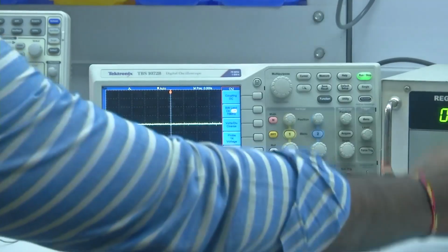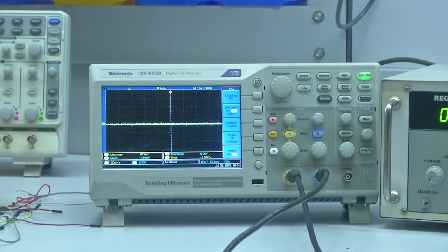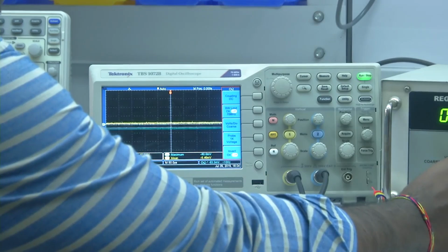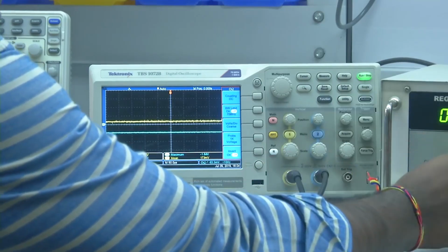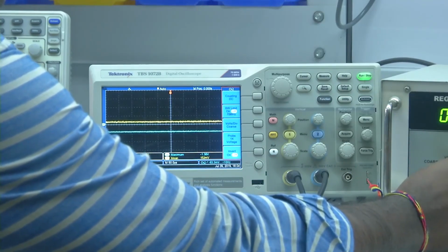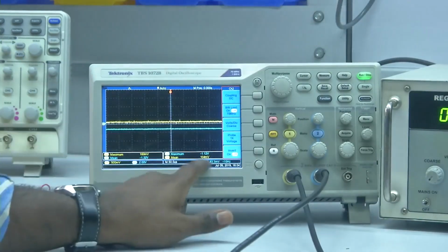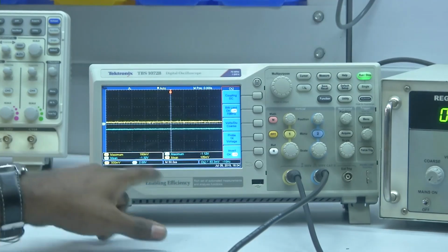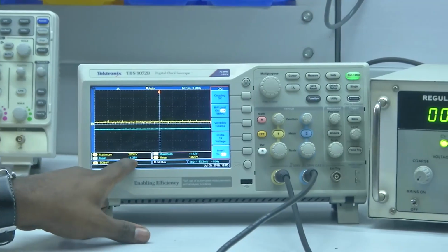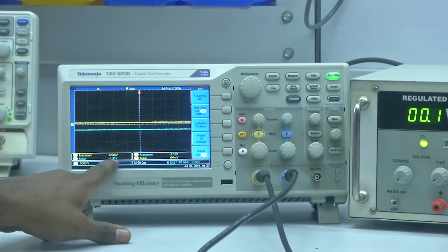Since the gain is 10, if we provide 100 millivolts as an input to the system, we will get approximately 100 into 10, 1 volt. But this is not the right way. Since we are testing our inverting amplifier configuration, we will provide the known input and measure the output side. Right. So, let me provide the input voltage. I am giving an input of 100 millivolts. Here, if you observe, the mean value is approximately 100 millivolts, the maximum is 160, whereas the output is 1.31 volts.